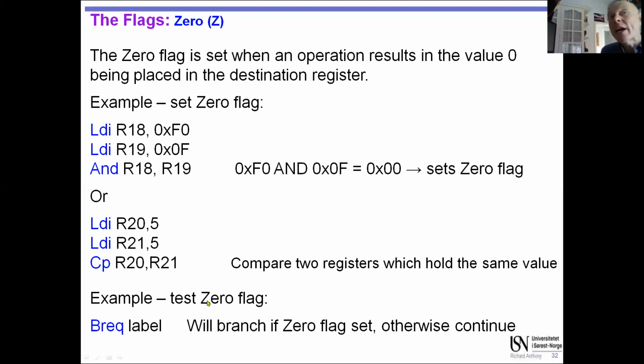So the 0 flag is also used to say equals. So if you do a compare, where is the result of the compare instruction? It's in the 0 flag. That's how it works. So again, you need to know these things if you want to understand in depth what is going on. That's how the next instruction could be a branch.